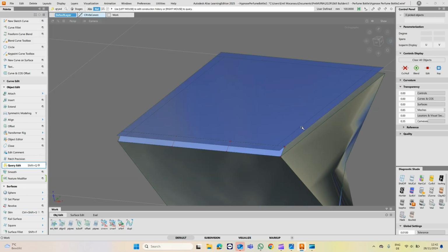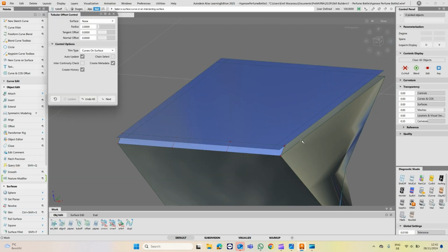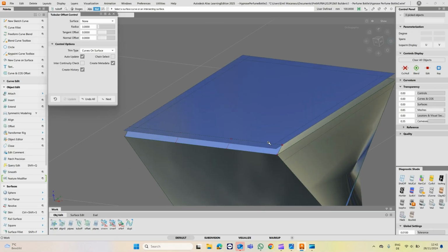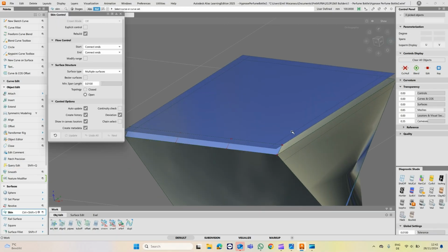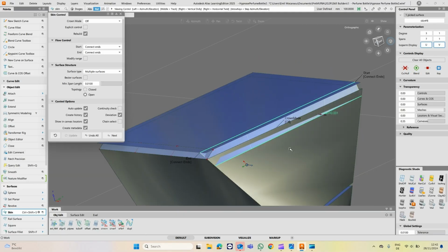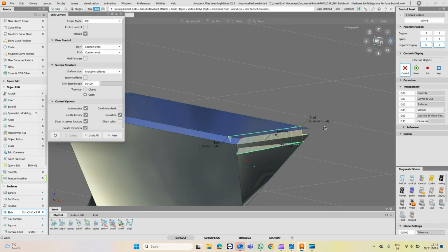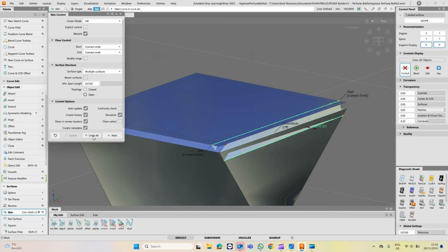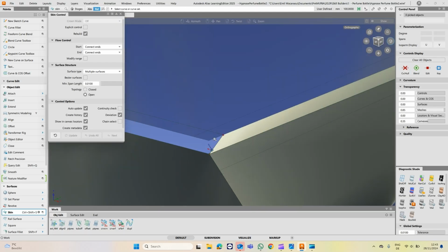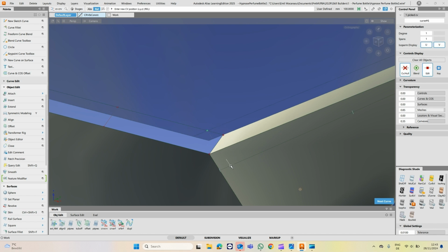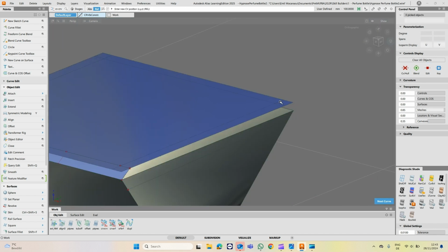And I can demonstrate that. Hopefully, if I run this here and we build a curved surface between this, we build a skin between that curved surface and this one. And you already see that's different. To overcome that problem, you would need to build one line from that point to this one, and one from that point to that one, and build a bi-rail.